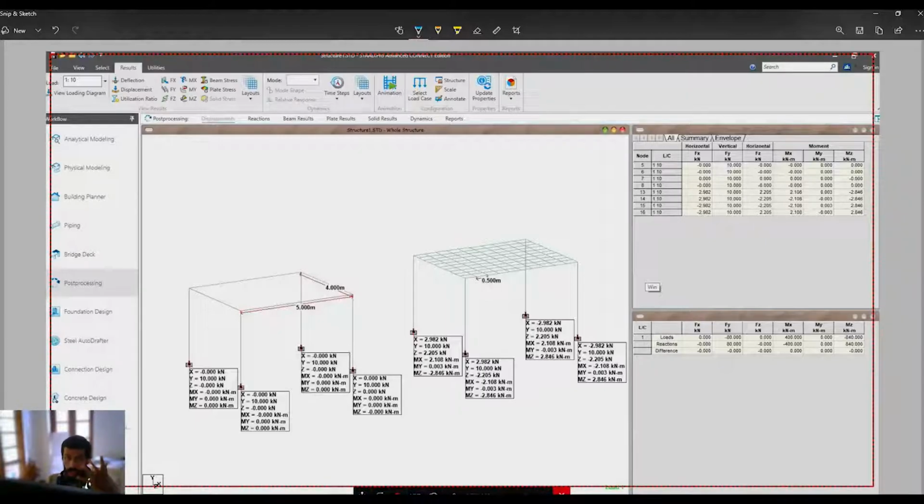So basically, if you apply any type of load onto this slab, it will always create a bending moment. As you can see, this is a slab, and if you apply any load right onto the center, that will eventually put a dip in the center, which will create a moment, which is not displayed in this case. You can see all the moments are 0, which is absolutely absurd. I can't believe the moment can be 0.